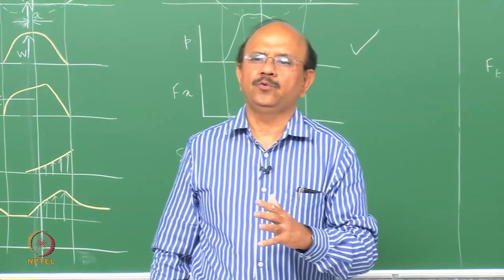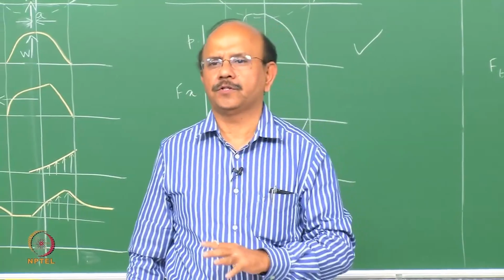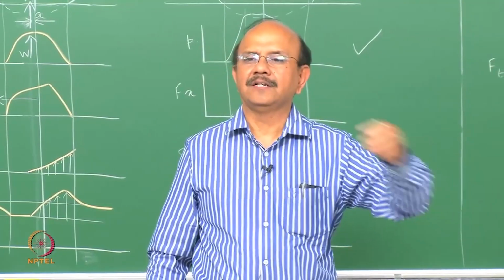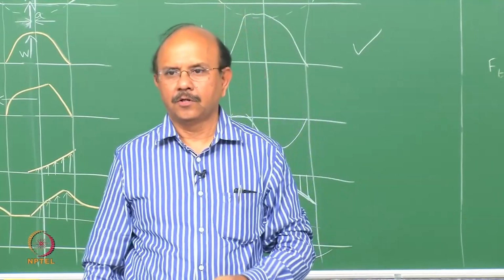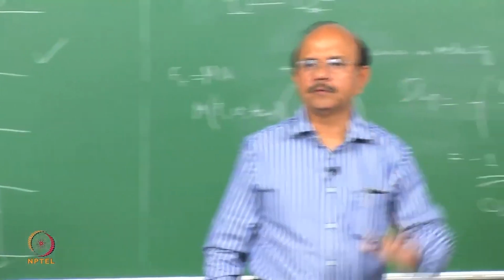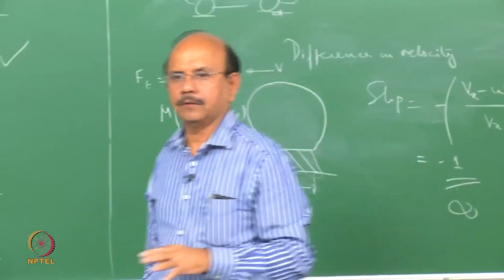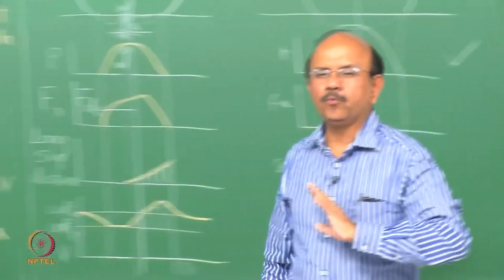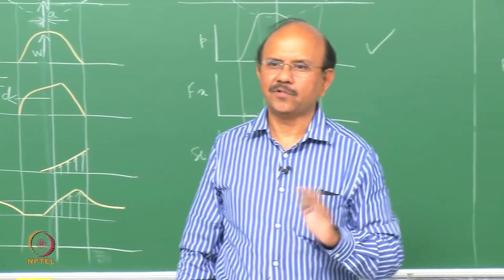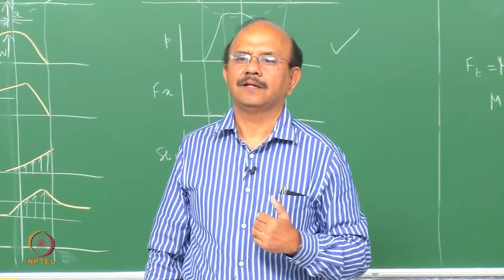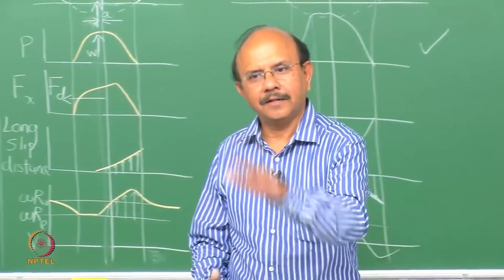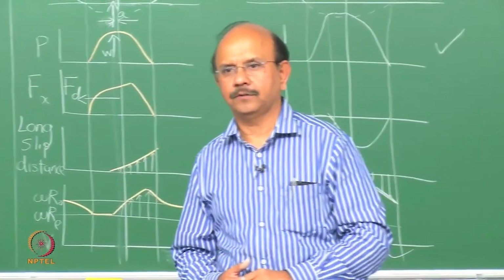So what people do is to follow Coulomb friction and say that the Coulomb friction, for example, for a truck tire is 0.75. Coulomb friction for a motorcycle tire is 1.02, and so on, right? So we sort of have an approximation which is not necessarily correct, but somewhere we have to start working, and hence we have to follow Coulomb friction.